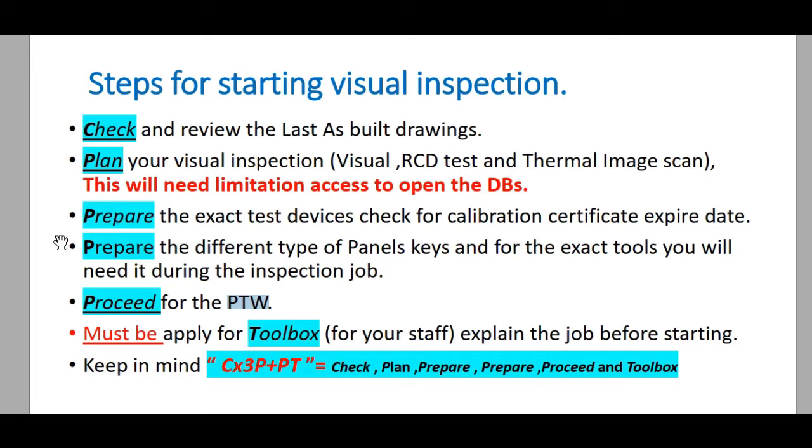The third point is that we must prepare the exact test devices. Check the calibration certificate expiry date. For all the devices that we are going to use during our RCD test or thermal image, we must be sure that these devices are calibrated and also have a certificate which has not expired.